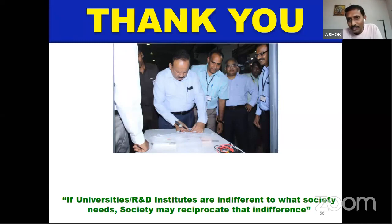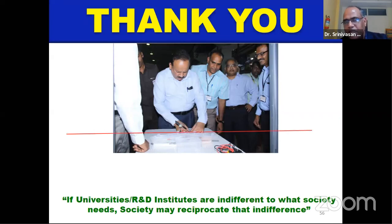So the first question raised by Venkatesh: what is the lifetime of the battery if it is used for 10,000 kilometers per year? For example, per charge you can go 100 kilometers. Usually that battery will last for 1,500 cycles. Not 15,000, 1,500 cycles. And per charge you can go 100 kilometers, right? So in that case you can go 1,50,000 kilometers.